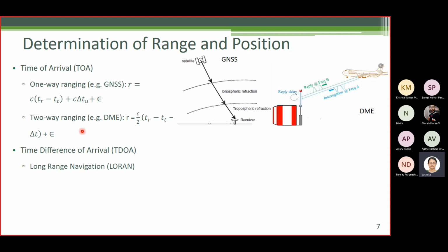But there is a fixed time difference between the master transmission and the secondary transmission, and it is different for different secondary transmitters. Now this fixed time delay is known. The nominal value is pre-calculated and known. It's called nominal emission delay. So it is known to the user. Once the user identifies the chain, he will know the nominal emission delay between the master and a secondary.